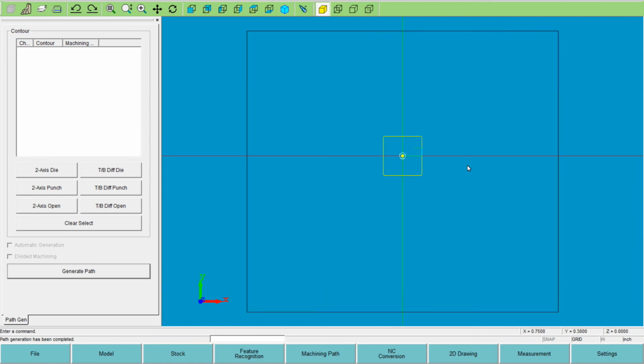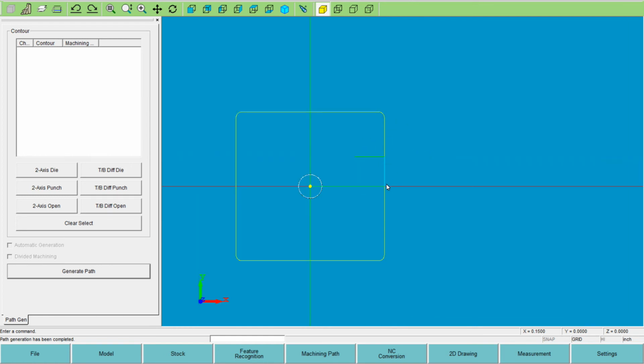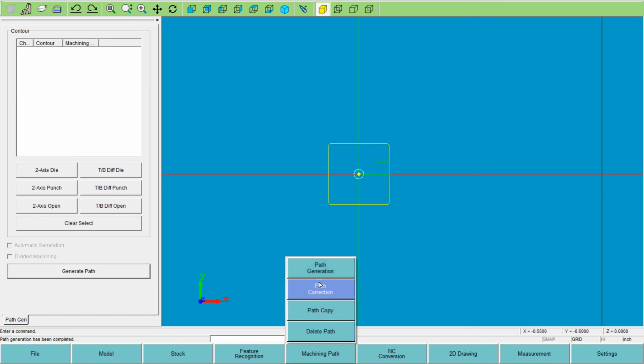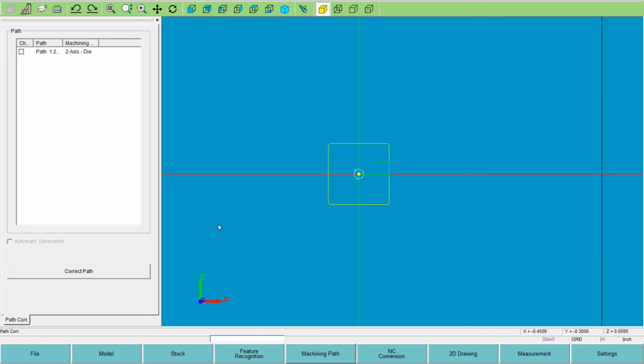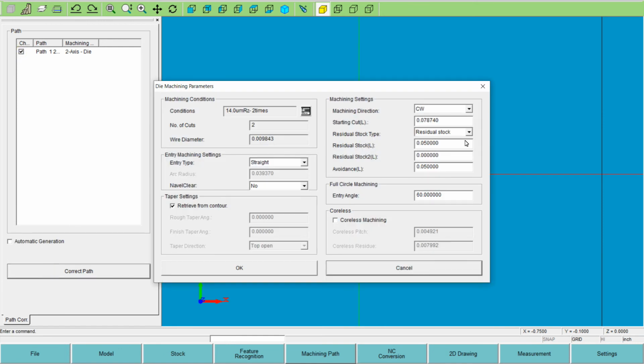We put on top view, so you can see your yellow tool path with the little blue. That's your stop distance, and this is the distance it retracts. So those two distances, let's go in here and let's turn on path correction.